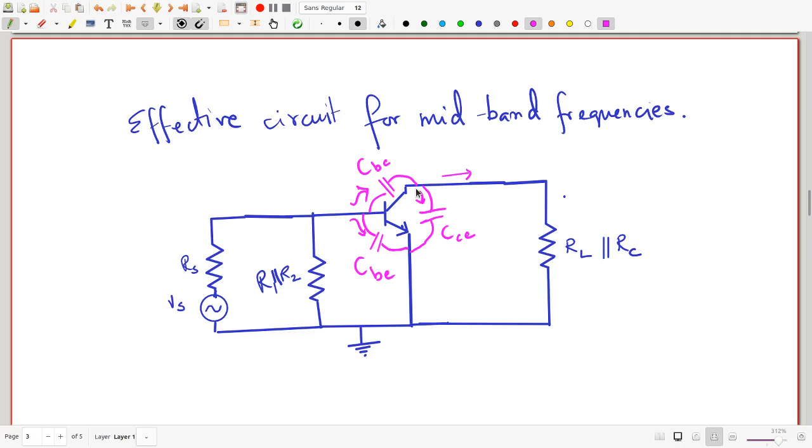All that will happen in low frequencies. In very high frequencies, on the other hand, these capacitors, the ones which you have connected, will behave like shorts, but these stray capacitors will provide alternative pathways for current to flow, again impacting the performance of your amplifier.